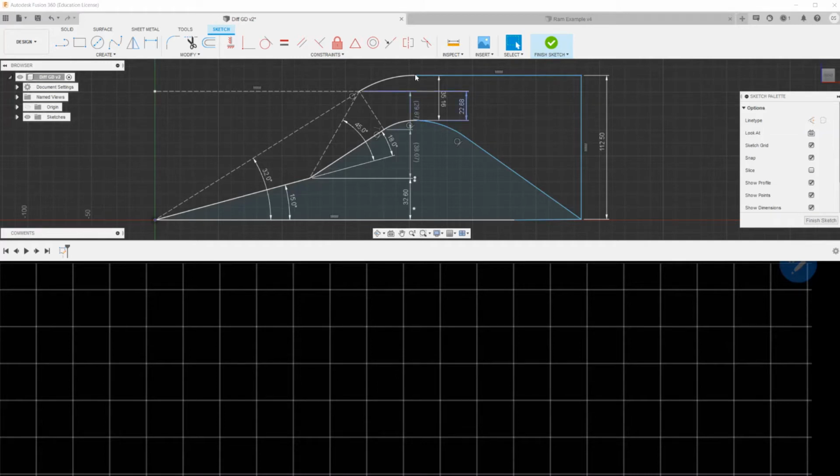What happens then when you constrain it too much? Your flow becomes supersonic, right, and starts to be supersonic in this region. Theoretically it can be supersonic in this region. I say theoretically because what happens in reality, when you constrain too much, is that the growing boundary layer will block the flow and will push outside. Pressure created in these conditions will make our normal shock wave stronger, much stronger.